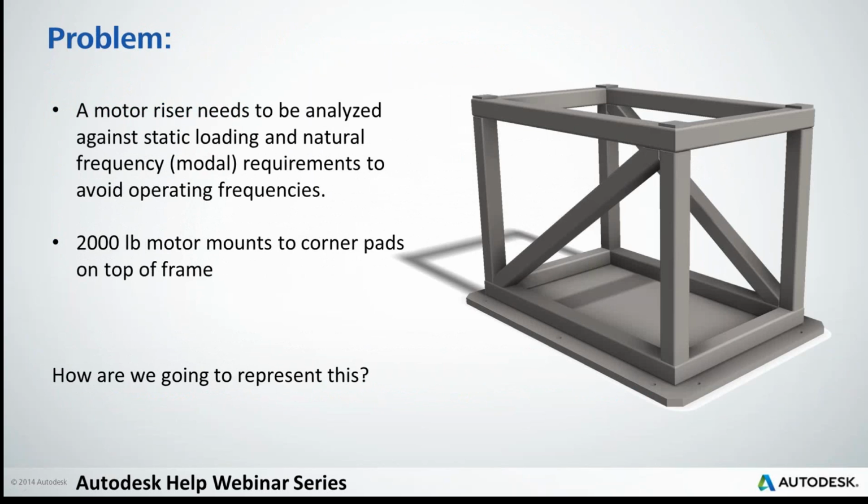So let's talk about what we're discussing here and why we would care. Here's our problem. We have a motor riser, and we need to analyze it against static loading and modal, or natural frequency. We have a few operating frequencies we need to keep out of our range, and a certain amount of load that this thing needs to carry. In this case, we have a 2,000-pound motor mounting to the corner pads on the top of the frame, and we also have a location for the center of mass.